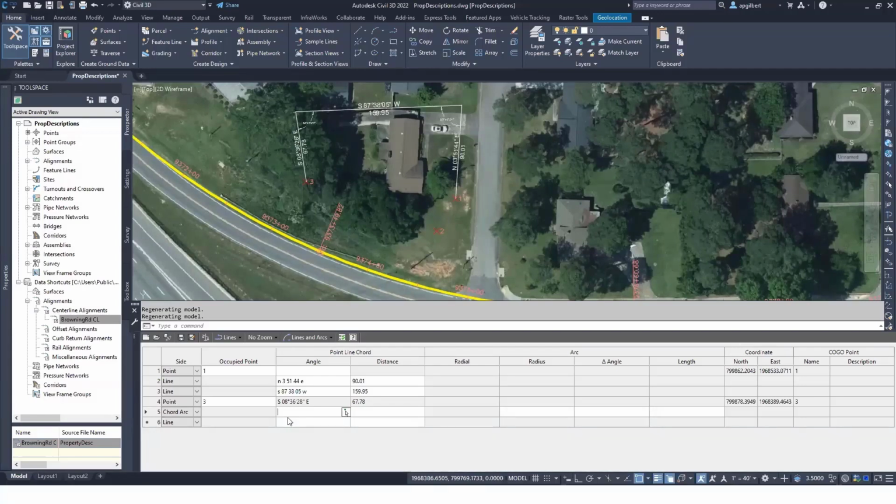Now, with this said, there's a ton of shortcuts available to enter angle and distance. If you go to the help file here, it's a great resource for all the different ways you can input. Like you can input meters or M and it will convert it to feet. You can even input chains. I could put 20C with no spaces. That'll be 20 chains or 1/4 of a mile. And I can put rods and links as well. So there's tons of ways to input.